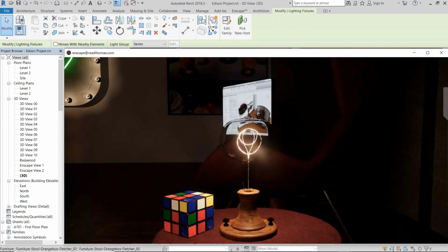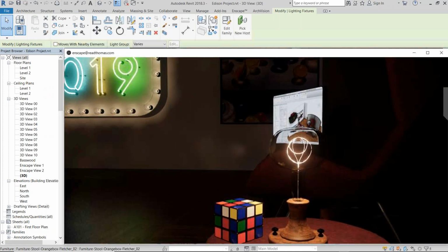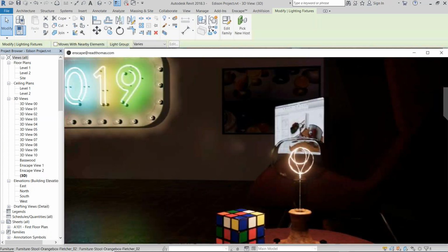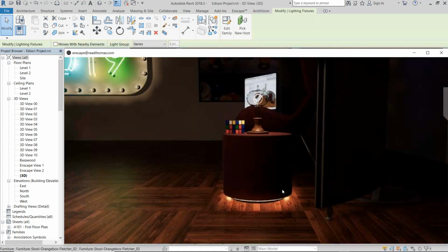So when you have very subtle lighting conditions that are strangely geometrically shaped, such as tape lighting, accent lighting, neon lighting, even these little side tables. If you have a piece of furniture that has the appearance of luminance, some accent lighting for that piece of furniture, you simply select the geometry, apply a material parameter with a generic asset type, and now you can check that box for self-illumination and give that geometry the appearance of illumination. Really, really easy to do.